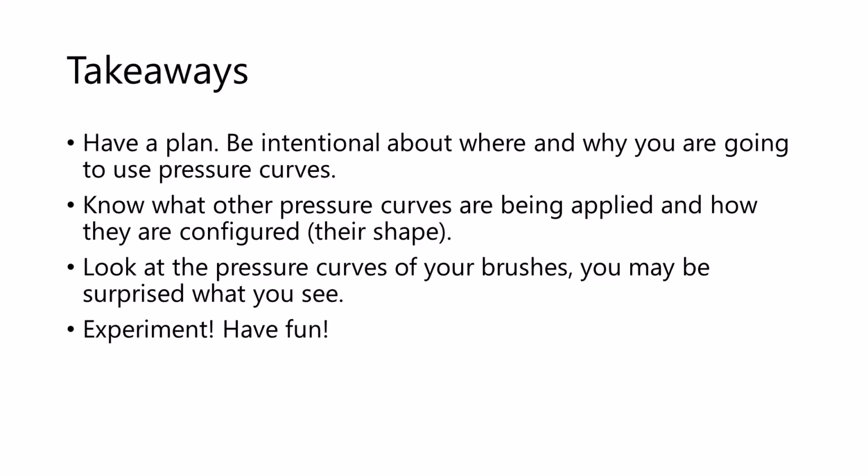So a few quick takeaways. We've seen so many places where you can modify pressure with a pressure curve. So you should have a plan where you want to set your pressure curves. I shared my strategy, maybe that will work for you. But in any case, find something that works and just be intentional about those curves. Because there are so many places where curves can exist, when you are modifying pressure, you should check into what's going on in all those places. Especially if you're trying to customize the behavior of a brush or are troubleshooting why something isn't behaving correctly, you might find that these other pressure curves are interfering with your goals.